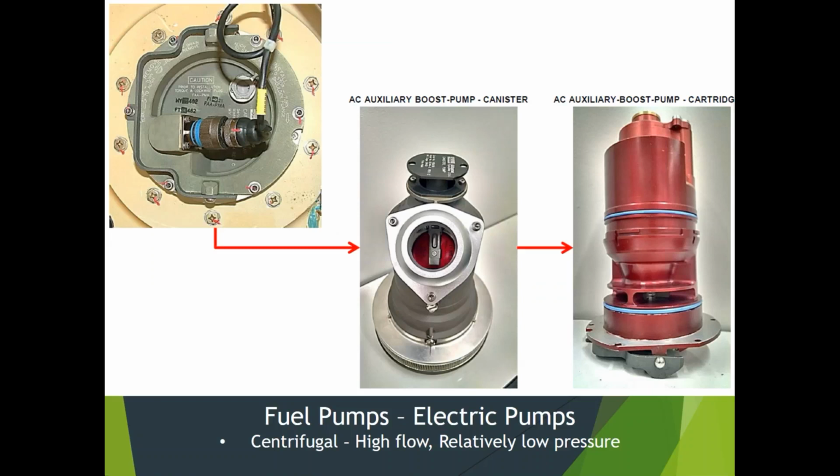You turn the pump, and then you remove a drain plug, and it removes any fuel. When you turn the pump, it closes all the valves on the cartridge. You open that drain plug to drain whatever residual fuel is in the pump, and then you can pull the pump out and not get a big shower of fuel. To put it in, you have the drain plug installed, put your pump in, turn it, and typically push it up and throw the handle over. Okay. And you can see there's a cannon plug on the outside for power.